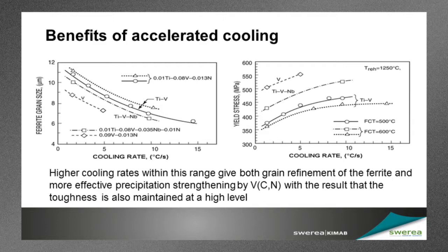Let's take a look now at the cooling after hot rolling. And what does this do for us? Well, one thing we can control is the rate of cooling by blowing air or blowing mist of water and air at the steel. So we can change the rate at which it cools down, particularly important through the transformation range to ferrite.